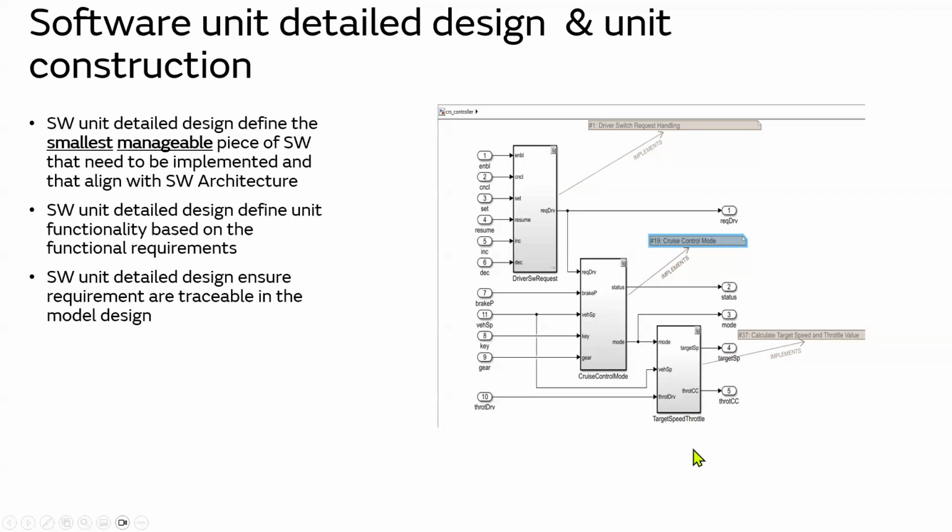So what we have done here really is trace the requirement into our software unit design in Simulink. So we have achieved traceability of the requirement into the model.